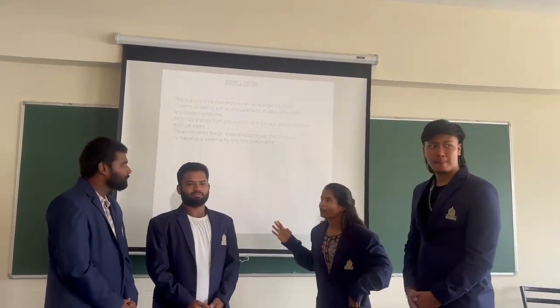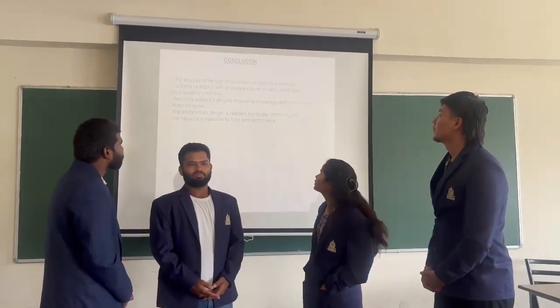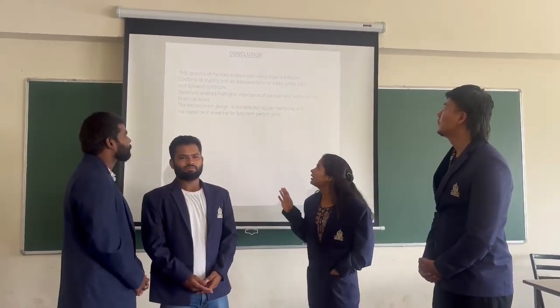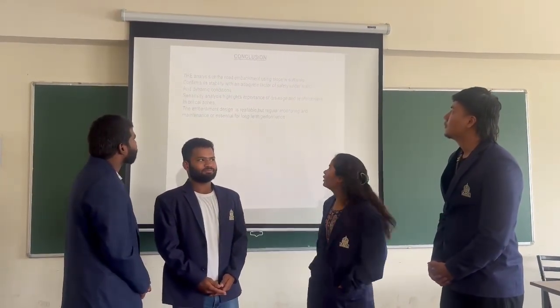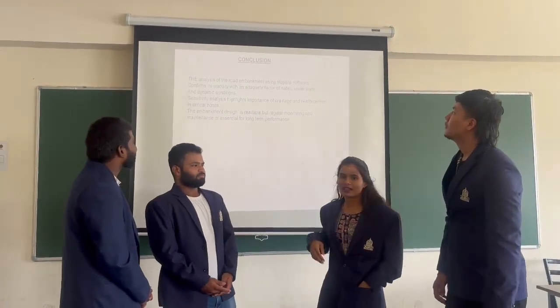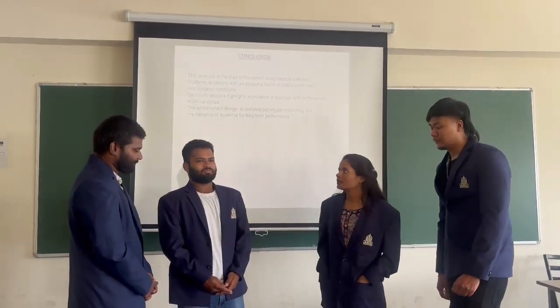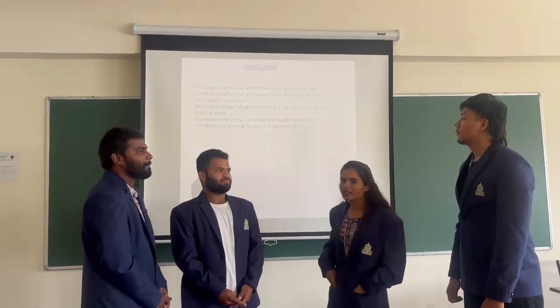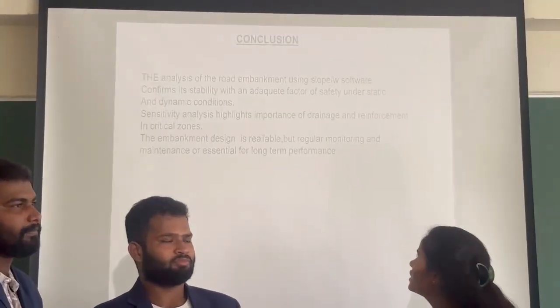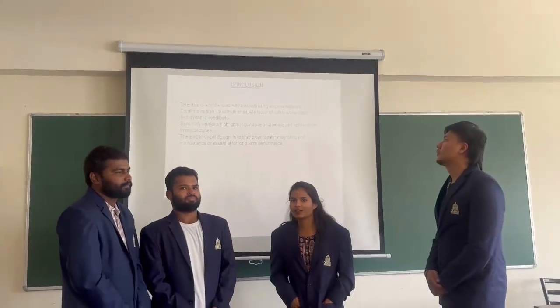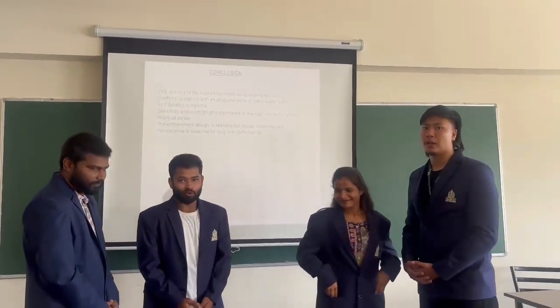Here is the conclusion. The analysis of the road embankment using Slope/W software confirms stability with an adequate factor of safety under static and dynamic conditions. Sensitivity analysis highlights the importance of drainage and reinforcement in critical zones. Thank you.